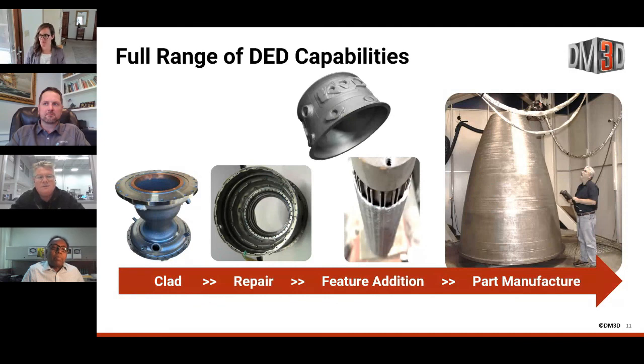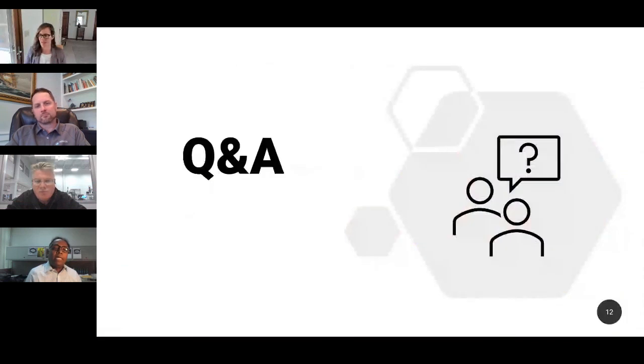But no, I was thinking more about additive machines where it takes place in a box. It's a start to finish process in one go. Correct. I perfectly understand, but I'm just saying, because the DED is a different process, in a big machine it gives you the ability to bring in the measuring equipment and intermittently measure it. If you're running the part for 700-800 hours, you may want to take a measurement every 40-50 hours to get at least some idea where the part is. I totally agree. That's quite possible with your situation.